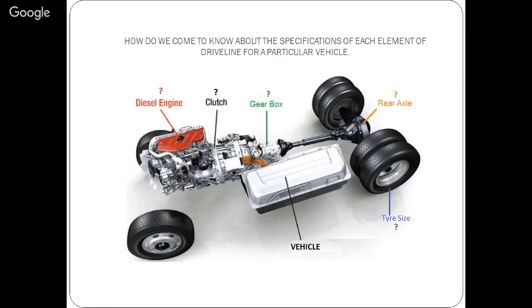We are talking about a truck segment, and now we have a small engine. Suppose this is a constraint. But my torque requirements on the wheels are more, so I will use bigger gear ratios to achieve the torque requirements.